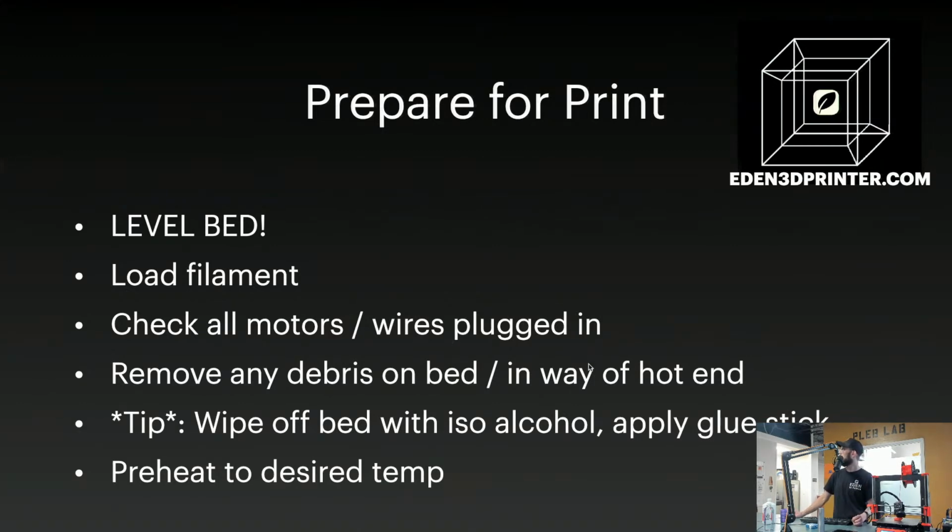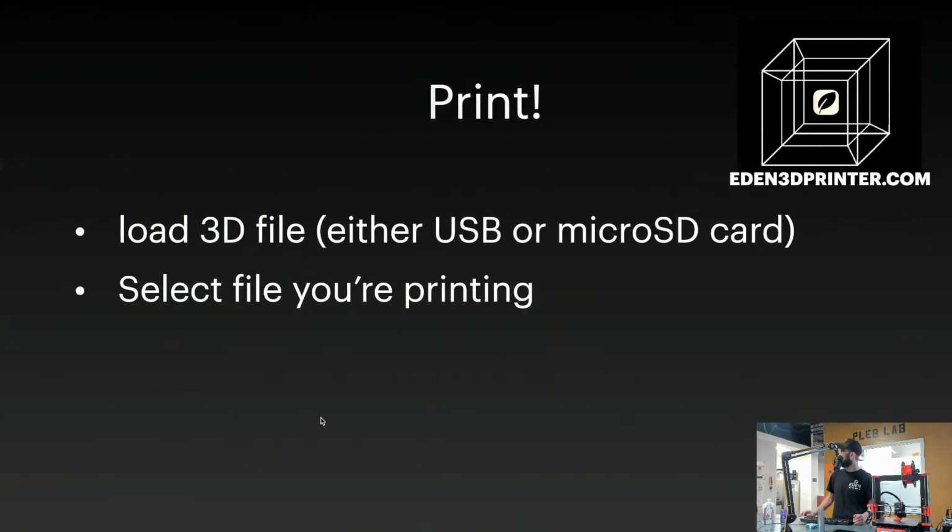And if you just remove any of the debris where it's building up, obviously, make it clean. As I just said, make sure you're wiping off the bed with either isopropyl alcohol. Honestly, soap and water work great. Windex is fine. Apply a glue stick if needed, not always, but if needed. Definitely do this when it's not hot, but it does help if it is a little bit warmer. It evaporates the alcohol or dries a little bit quicker. And of course, you're done.